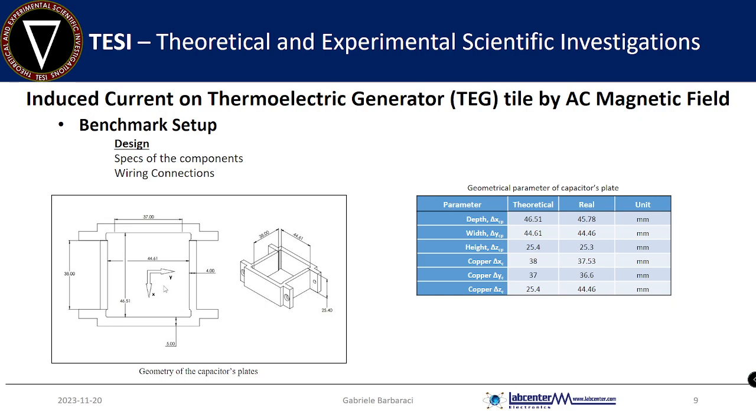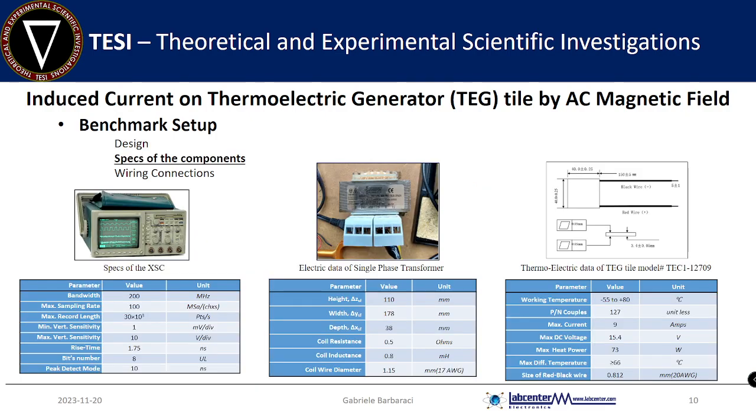So we have 46.51 and 44.61, but be careful because they are subject to very strong tolerances, due to the fact that when the print cools down, it tends to deform the initial shape. So I reported some of the dimensions in this table so that you can carry out by yourself, with some very trivial calculations, the values that we are talking about in this presentation.